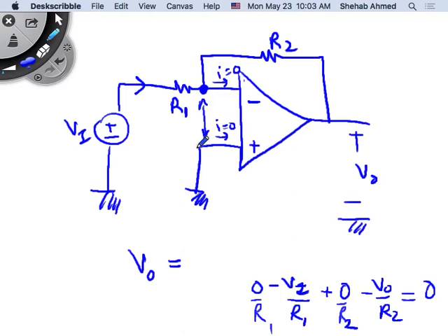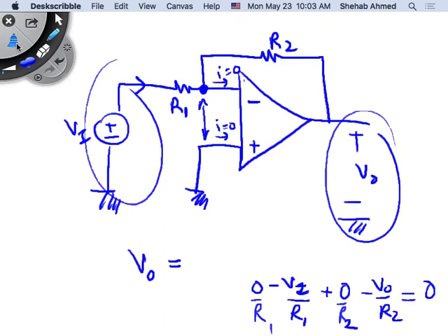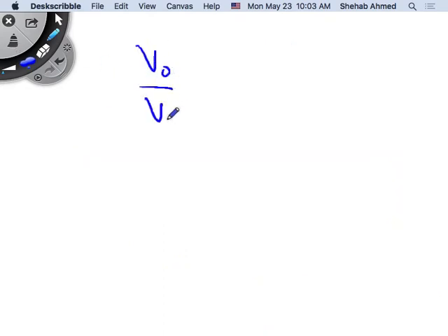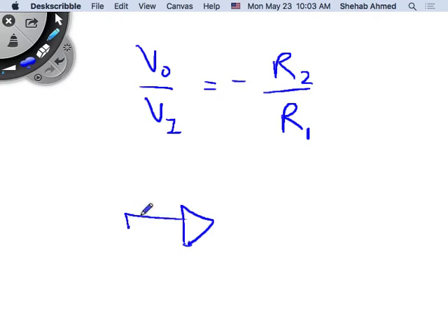So this is the understanding of the op-amp, the new addition to what we did. You probably did that in the last class, but we will build upon it. This is a simplistic view of it. We're going to be looking at more complicated views of the op-amp next year. So we now have an expression for V output over V input. V output over V input is now equal to minus R2 over R1. It is this feedback resistor over the input resistor that I have.